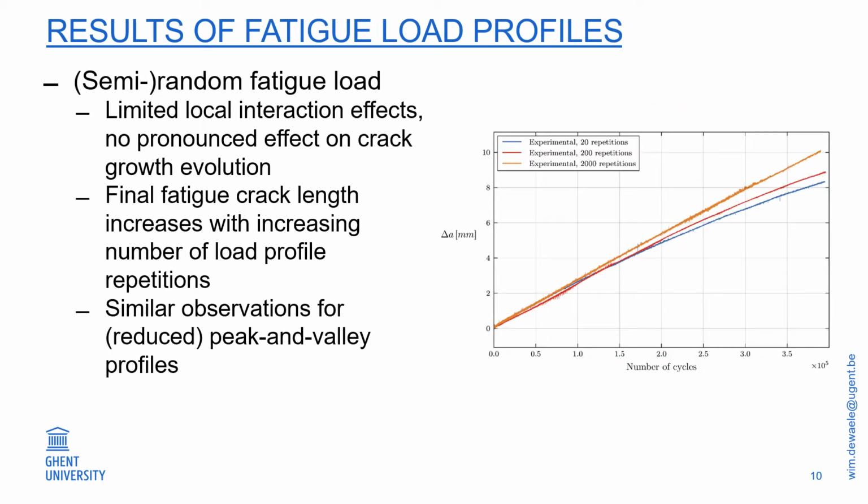This slide shows the results of the fatigue tests using the random load profiles. If you look at the curves, they are of a quite continuous nature, so there are no distinct or very discrete events of crack growth retardation or crack arrest. What you can see is that the more repetitions we used, the larger the amount of fatigue crack growth rate.